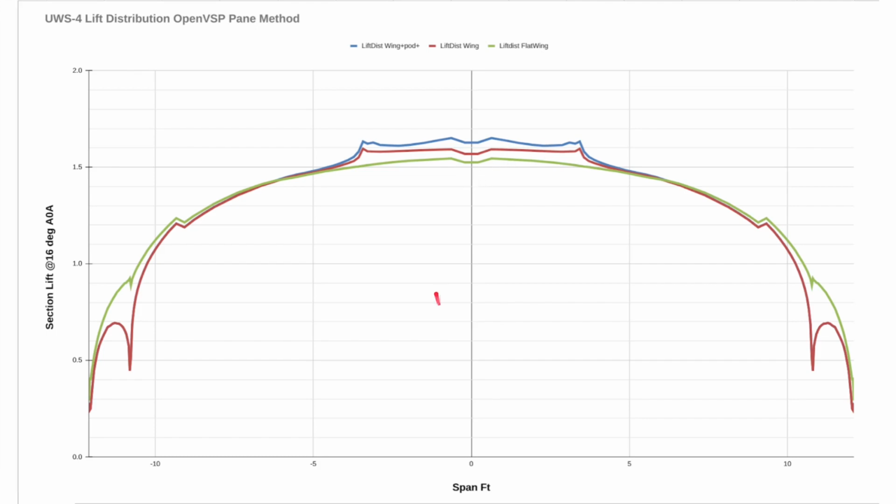Now in the real world, you will typically see a drop in lift any place you have something like the fuselage or a boom or a nacelle attached to the wing. So where the fuselage is, there we should have a drop in lift, and where the booms are, we should have a drop in lift. But the VLM method that I used to do this calculation has a little bit of trouble dealing with non-flying surfaces. But I would like to point out that the boom and fuselage I am using will not have quite as much of a loss in lift as a typical fuselage or nacelle.